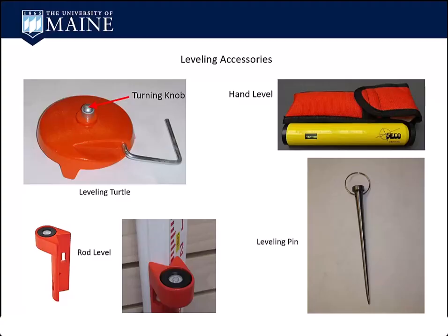With the knob on a turtle, you can do that. You can do the same with a leveling pin. A little more convenient to carry. If you need a good place to turn, you just jam that into the ground, and it's good enough for a turning point, because turning points aren't something that you're going to want to recover in the future.